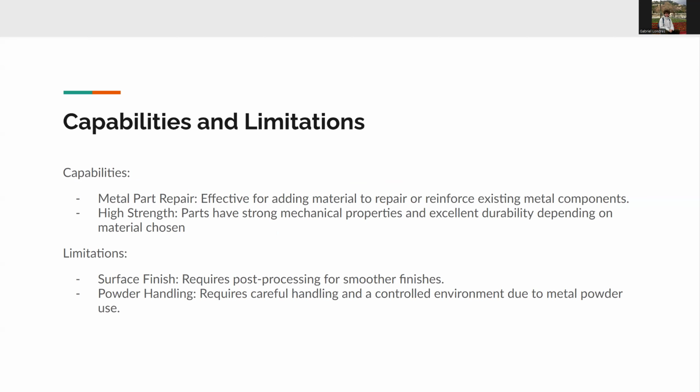So a couple capabilities and limitations of this. Metal part repair: it's very effective for adding material to repair or reinforce existing metal components. Parts have strong mechanical properties and excellent durability, depending on the material chosen. A couple of limitations of this: the surface finish is rough sometimes, so it may require post-processing for a smooth finish. And powder handling requires very careful handling and a controlled environment due to the metal powder being extremely fine and easily inhalable.